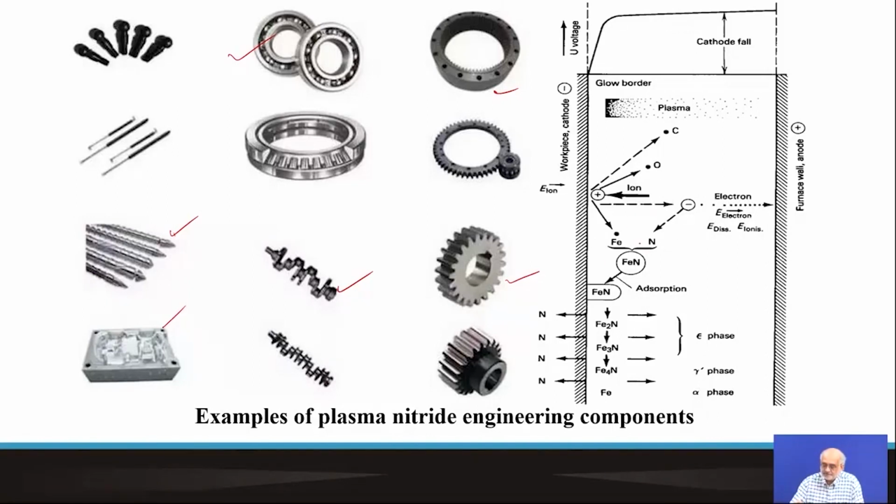This is no different. Initially, when nitrogen gets dissolved in iron, we form solid solutions. The solid solutions could be in the BCC state itself. If you dissolve quite a large amount, then you can even convert that into austenite, and that austenite can get stabilized. Apart from such solid solutions, various forms of nitrides may form: Fe4N, Fe3N or Fe2N. So initially just the dissolved phase, extended austenite, then epsilon nitride, even zeta nitride, and so forth.